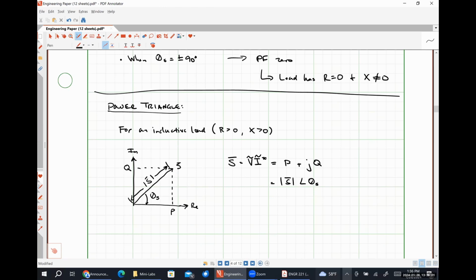Average power is the same thing as real power. Yes, absolutely. Yes, sir. Rectangular, exponential, and polar. That being said, me personally, 99% of the time, it's going to be in polar form. The other 1% is split between rectangular and exponential. I effectively never represent an RMS phasor voltage or a phasor voltage as a rectangular form complex number, practically never.